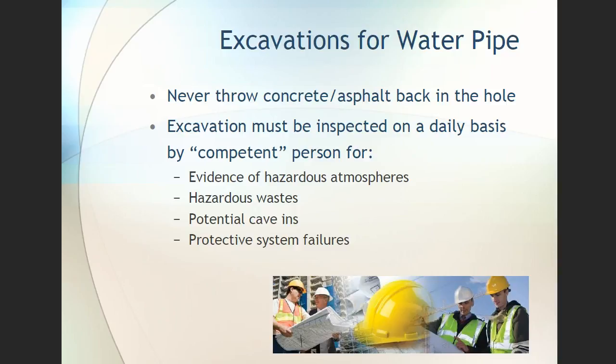Excavations for water pipe. Like I mentioned, you would never want to throw concrete or asphalt back in the hole. You've seen these big ditchers that they use in installing pipeline, the ones with a really big wheel. They're like 14, 16-foot wheels with diamond blades that go right down the street. Those actually have a situation that's designed into it where when it pulls out the dirt, it puts it through a screen and removes all the rock and debris. And then that clean material, which is piled along the side of the ditch in a nice, neat manner, getting ready for backfill, is called shading.